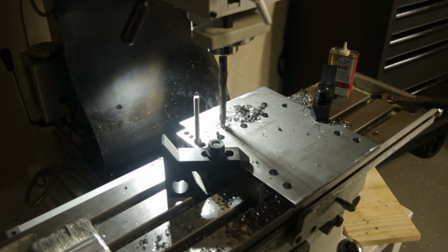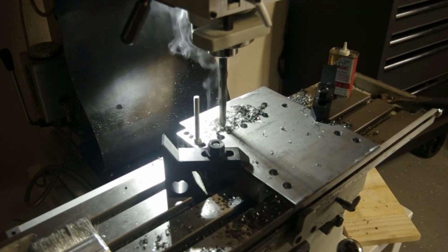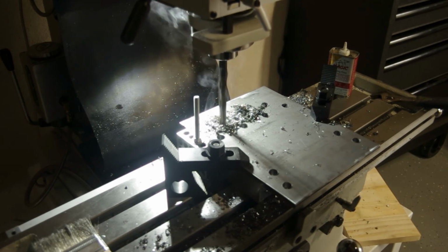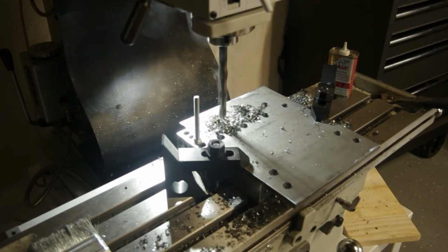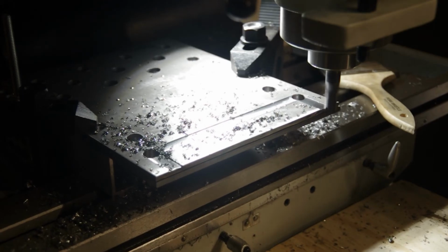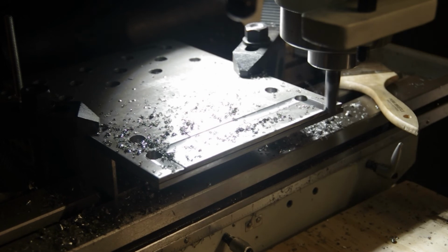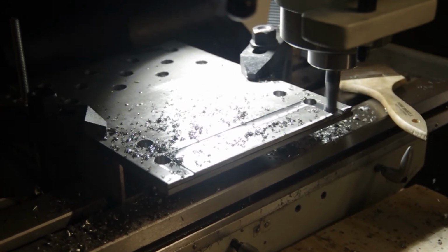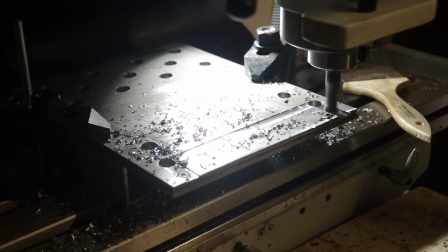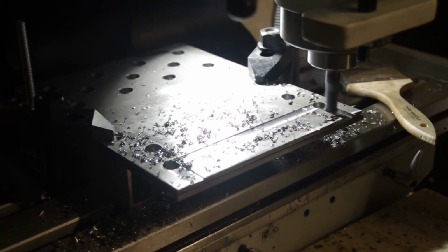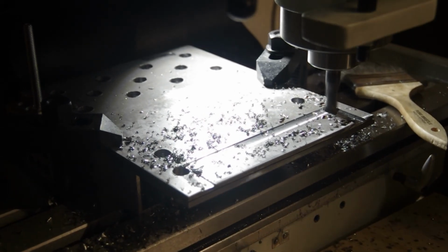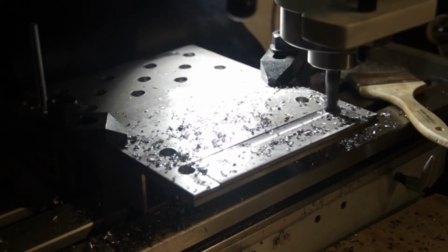After getting everything cut and deburred and cleaned up, I took the parts over to the mill and started drilling a bunch of holes for the burner. The holes are there to allow some of the heat to get out and to actually see what's going on inside. But they're also there to help keep the heat in. Since it's not a very large burner, you don't want a gust of wind coming along and extinguishing the fire or blowing ash out.